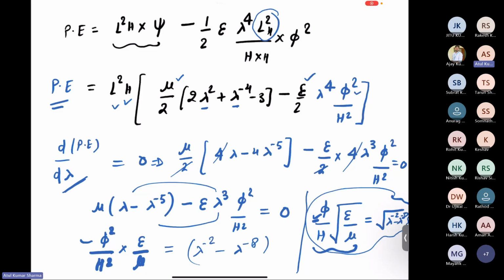Okay, you know that for a spring force system, if I apply 10 Newton force, and if you know K, then U, or the deformation, will be F upon K. Similarly, now if I know the material parameters for a real case, let's say for the VHB tape that Aman talked about in a previous talk, for which let's say epsilon is 4 times epsilon naught, and shear modulus is let's say 30 kPa or 40 kPa, whatever value you take, and let's say the thickness of that VHB before deformation is 1 mm.